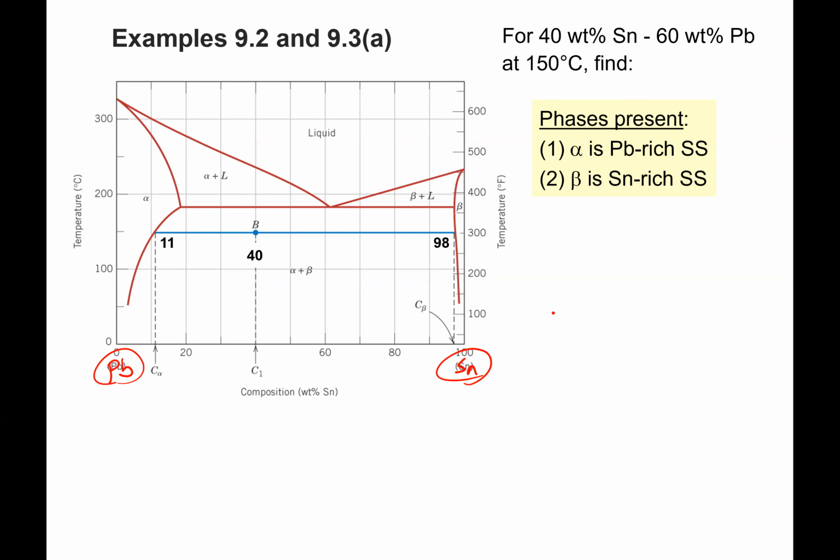We kind of talked about that. In the eutectic system, you've got this nice eutectic point where you have an alloy, so you can get solid solution strengthening, but you can also melt it at a lower temperature than either component, so it doesn't take as much energy and it's relatively easy to melt. And so these eutectic systems are nice for solders. All right, let me get off my little sidetrack there.